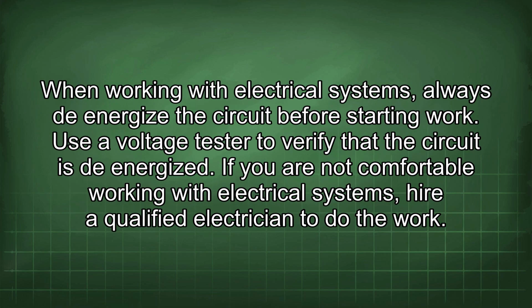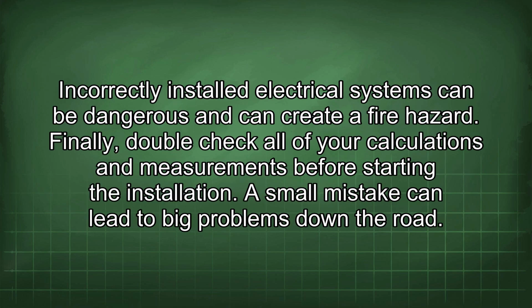When working with electrical systems, always de-energize the circuit before starting work. Use a voltage tester to verify that the circuit is de-energized. If you are not comfortable working with electrical systems, hire a qualified electrician to do the work. Incorrectly installed electrical systems can be dangerous and can create a fire hazard.